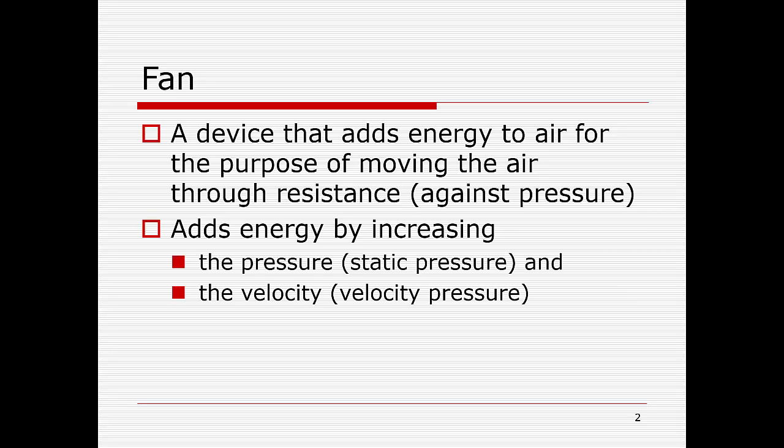A fan is a device that adds energy to the fluid, typically a gas, for the purpose of moving air. Okay, so it basically adds the energy by the static pressure, if you remember, and the velocity pressure PV. If you remember, the total pressure is static pressure plus velocity pressure.